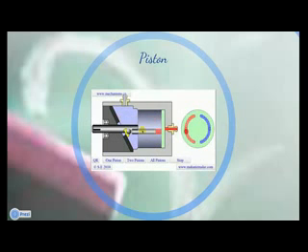The view of this port plate is shown as if an observer is looking at the pump parallel to the rotating shaft from the yellow port location. As you can see, there are two crescent-shaped gaps on this plate that are shown by the red and blue colors. The red indicates the high-pressured oil, and the blue indicates the low-pressured oil. The same color convention is true for the oil inside the cylinder.